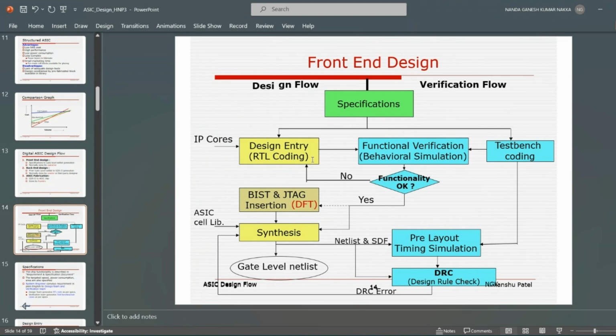Block will be delivered by the RTL engineer to the functional verification team, and if he verifies and says that the RTL has issues, but it is matured up to 50% or more, then okay, we can use this particular initial RTL for DFT flow bring up, because for this particular project again every ASIC flow owner has to develop the flow.